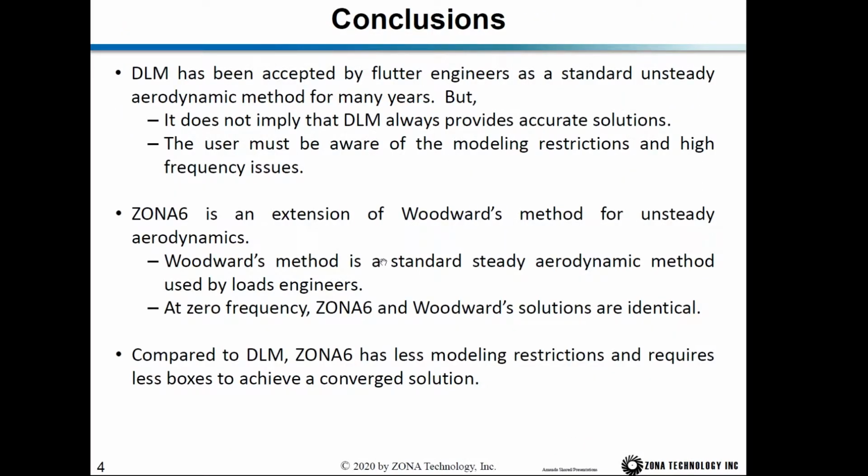So the conclusion: the DLM has been accepted by flutter engineers as a standard unsteady aerodynamic method for many years, but it does not imply that DLM always provides an accurate solution. The user must be aware of the modeling restrictions and the high frequency issues.